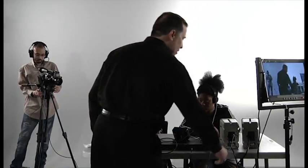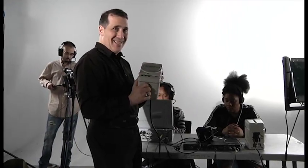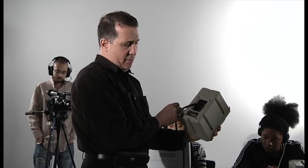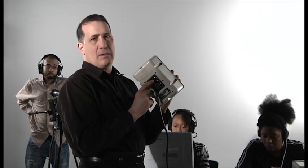We also have the ability to use speaker systems in this room or a room like this. We have an amplified speaker, meaning it has an amplifier built into it. This amplified speaker has multiple inputs. One is a line input and one is a microphone input. Basically, it's the attenuation of the signal. Line is, of course, more powerful than mic. These are 1/4 inch inputs. These are not RCA. These are not 1/8 inch. These are very big inputs, not quite as big as XLR. So we need an adapter to go to this input.